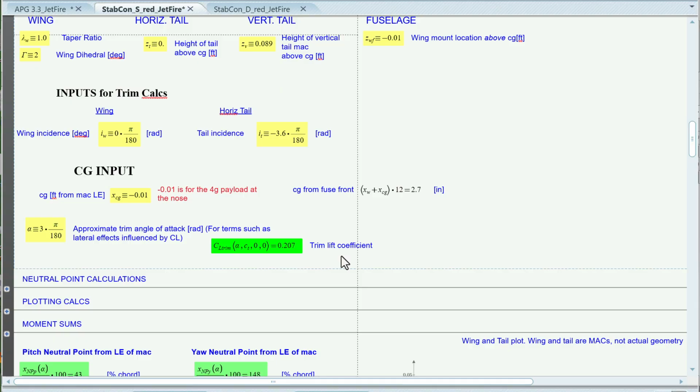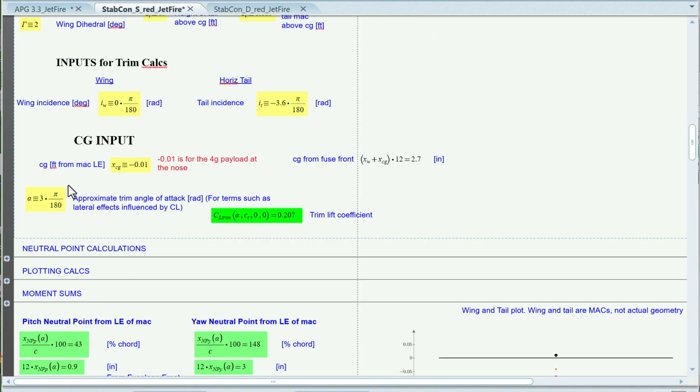Now the angle of attack is going to give you the best performance. That's where you're going to learn here that your stability and control can actually benefit your aerodynamics. The pilot's not having to maintain this. You're designing this airplane on its own to fly at whatever angle of attack is best for your particular mission. So I'm just going to keep it 3 in this case.